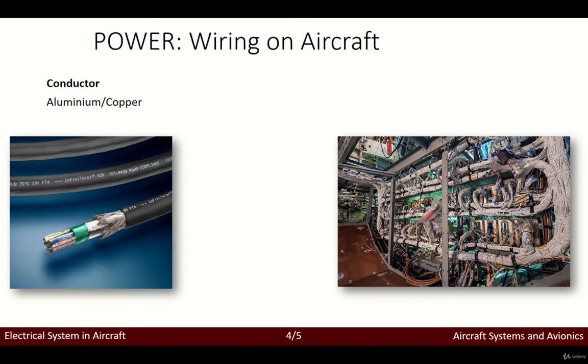Its lightness makes possible long spans, and its relatively large diameter for a given conductivity reduces the corona, right? So this is the discharge of electricity from the wire when it has a high potential. This is a bit technical, but it's actually an advantage. The discharge is greater when small diameter wire is used than when large diameter wire is used.